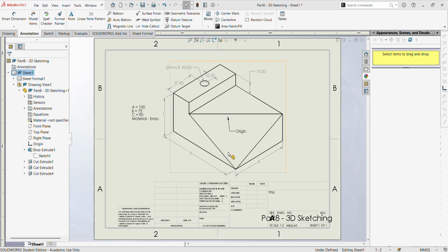And then the last thing we're going to touch on is this weird triangle cut out of this square box. There's not a lot of easy ways to do this. We've talked about it before. You can make a sketch, and you can make another sketch, and you can extrude cut that sketch along the sketch that you have drawn to be your path.